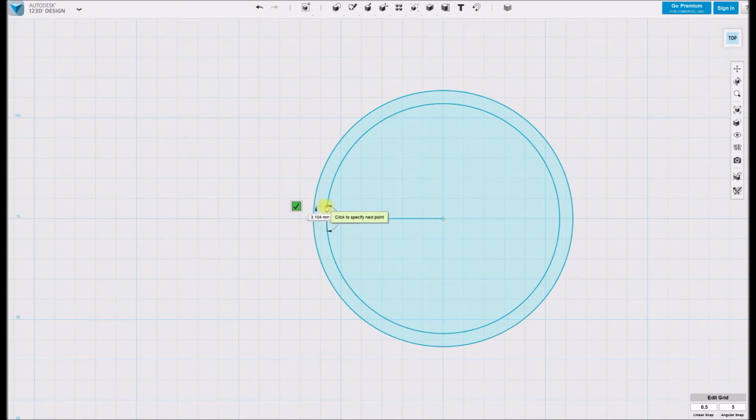So now it's going to be half of the large dimension on the back, so that 4.5. So that's going to be 2.25 because I'm starting in the middle. Oh, that's on the angle there. So tab to switch, 2.25. Enter to lock it in there. I want it to be 180, so I do want to lock that. So then same thing, escape, tab, escape, to make that free again. So the dimension, as we went over before, is 3.75, and since I mentioned that they're all 60s, we're going to go with 60 degrees, enter.